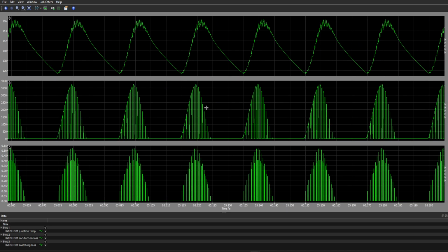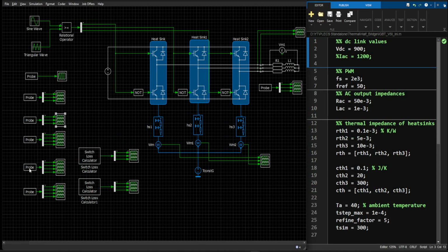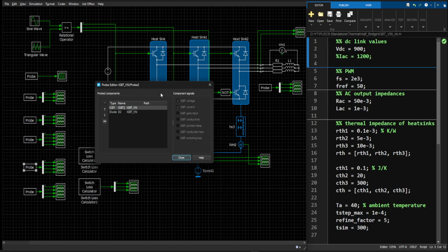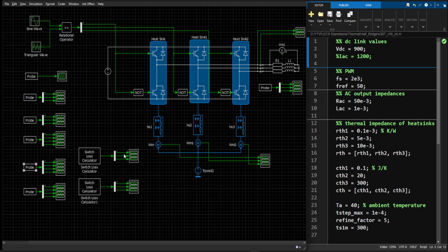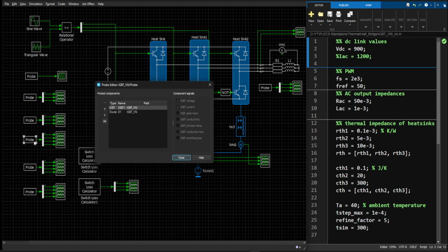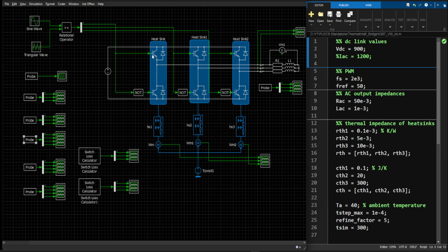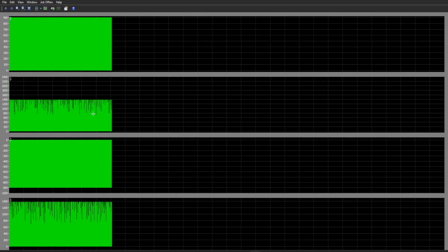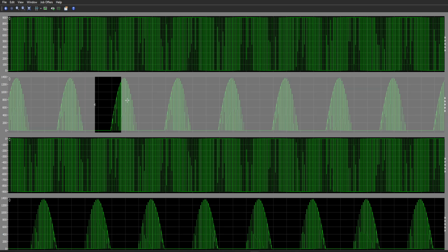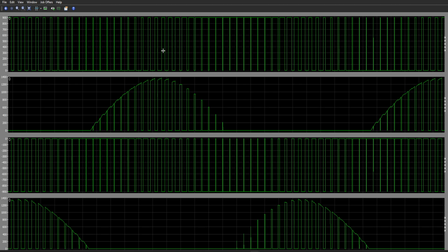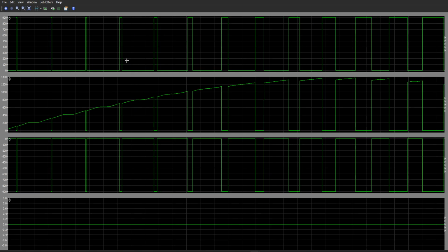What do we have more? We should also have the diode parameters. Let's check the diodes for IGBT2, or maybe here as well. Yes, let's take the first diode and IGBT from leg 1 and see their characteristic curves. The first two are for IGBTs. That means when the IGBT is conducting, the diode is blocking. How to see that? We need to look into curves 1 and 3.